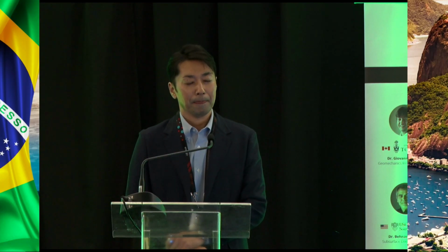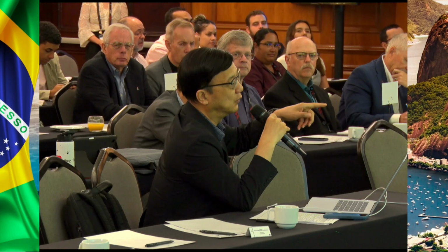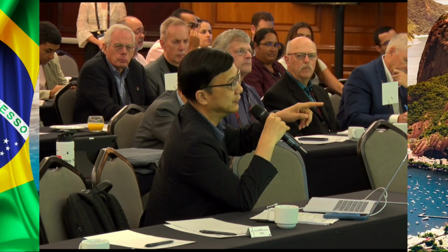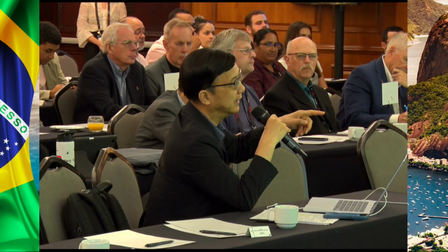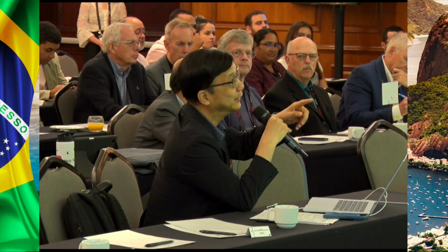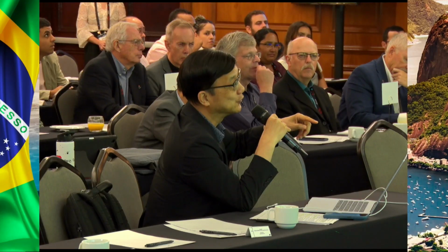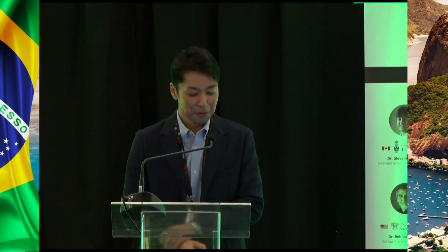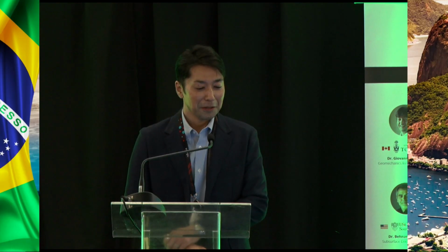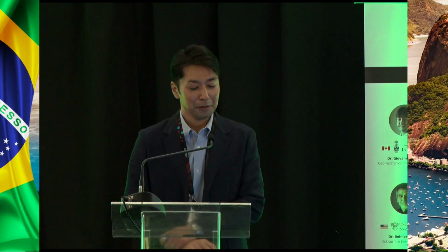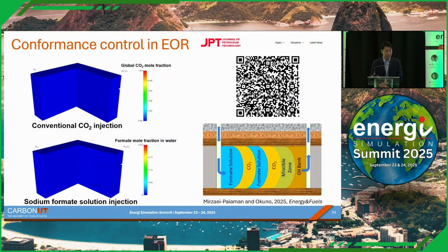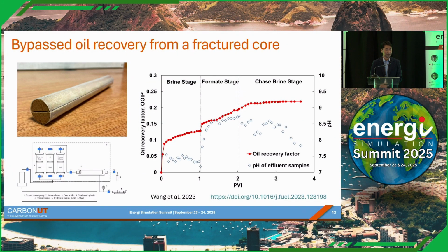Right. Now you had a core flood with water flood and then formate CO2 flood. Do you have a base case where you have water flood and then CO2 flood and then the formate CO2 to show that that's the case? Great question. So we did this alternating injection of sodium formate and CO2 in a simulation-based study, but not yet implemented in lab scale experiments. So that's a great question. We would like to work on it.